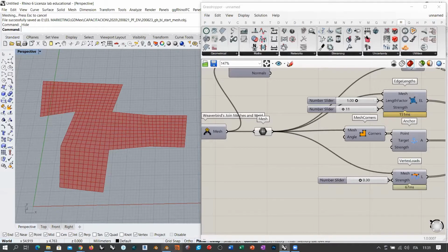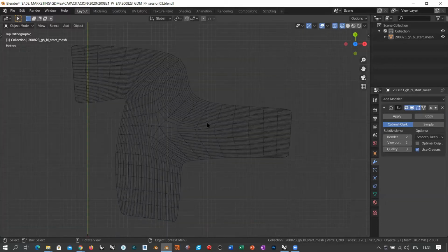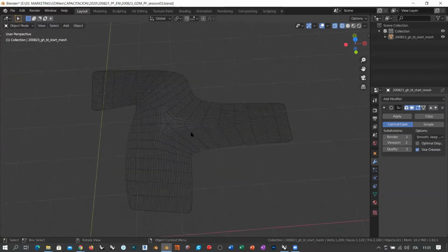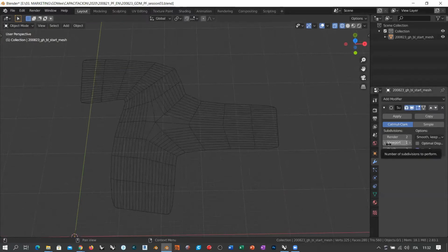But in this Blender mesh, things are a little bit odd if you think about it. One thing that we can do in order to come up with a more regular topology, in this sense of the aspect ratio, depends on the resolution that we want to achieve. Actually, this with 2 subdivisions is quite high resolution. So let me decrease this one step.